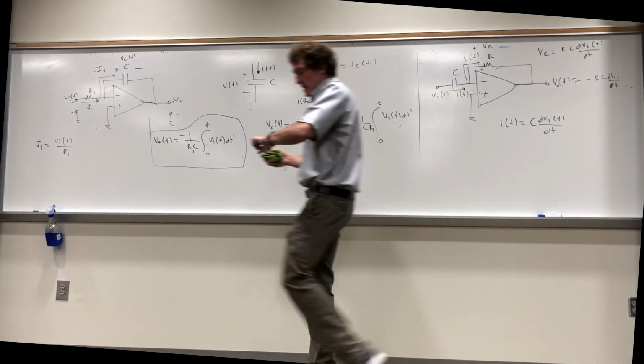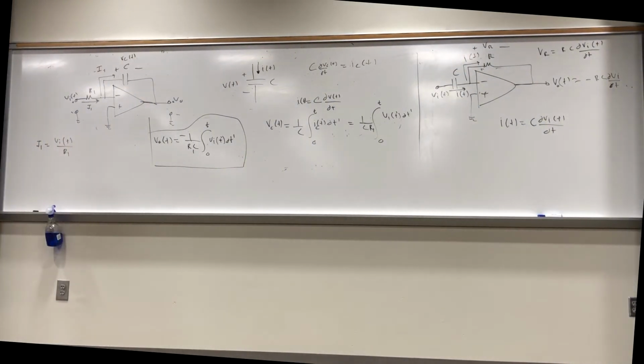Finally, the next thing is, now with operational amplifiers, I'm not going to work in the time domain. Usually when you do this kind of stuff, when you're building circuits to effectively simulate transfer functions for anything, the H of S, you work in the S domain, and there's never a cause for concern of initial conditions.